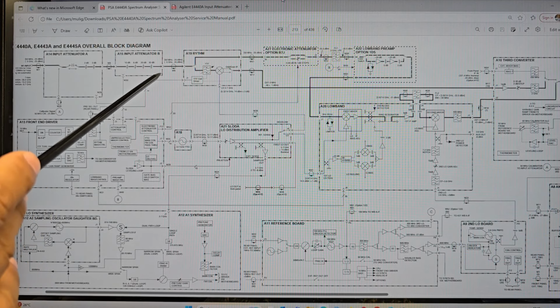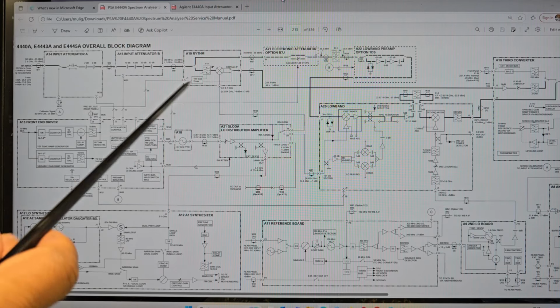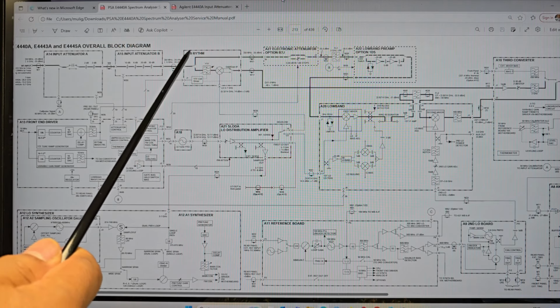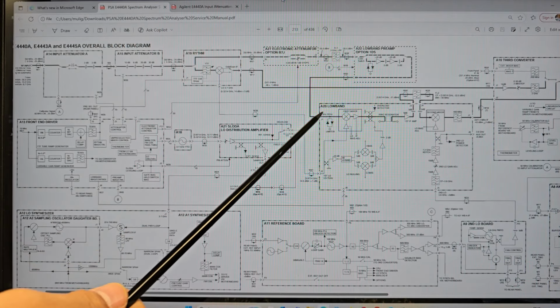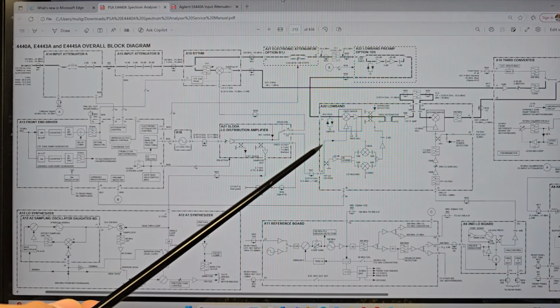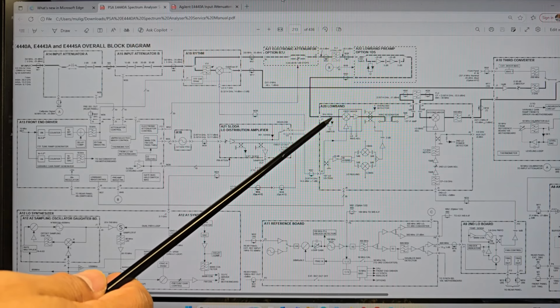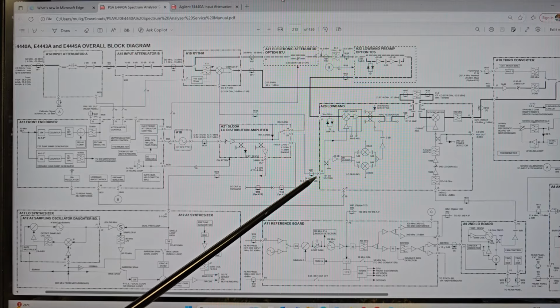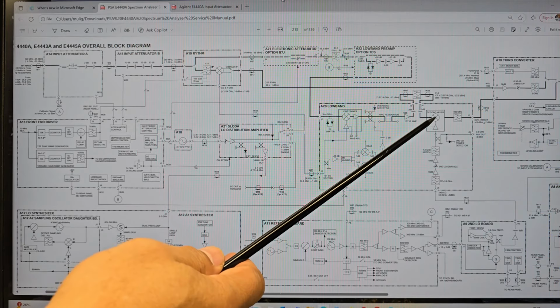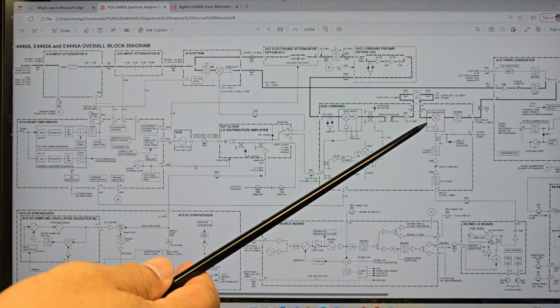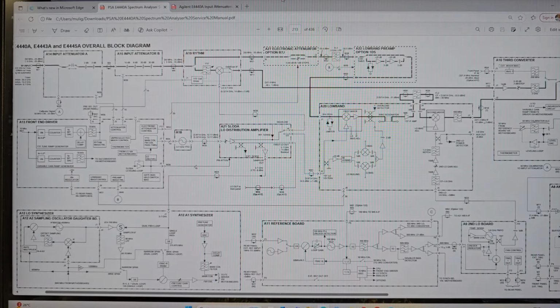This one has relays inside and goes into the mixer, and we can follow the signal path here. And this is the first local oscillator. If we have a problem with the signal in the first local oscillator, then we won't have any output here on the mixer.